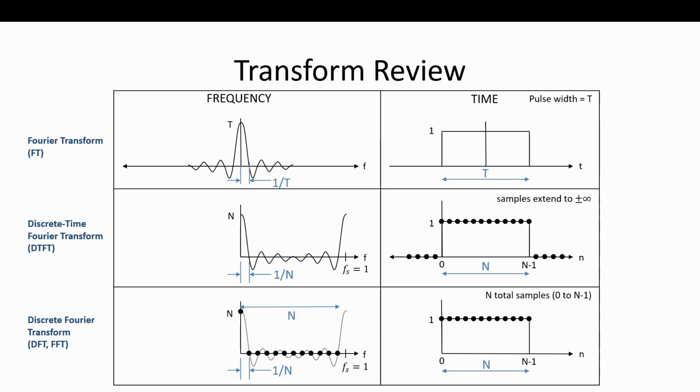If you zero pad it, you'll get more samples in frequency, because it has n samples in time, n samples in frequency. You know where those samples will be? Those samples will be right on this dashed line. So it's a perfect interpolation of that ultimate continuous DTFT that you want. So that's how you can plot the DTFT. Just zero pad the heck out of it, and you'll get something that looks like this, at least for your plot.